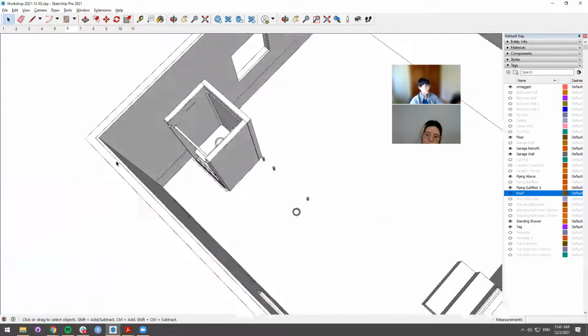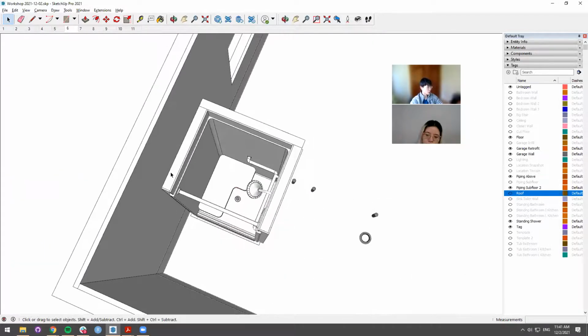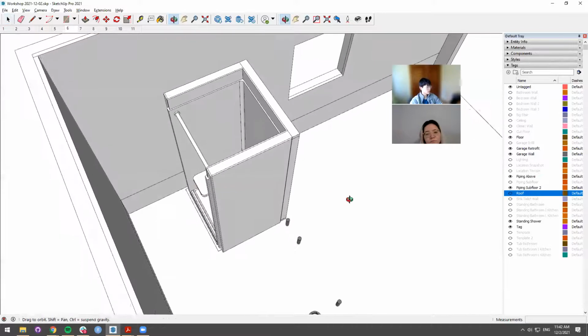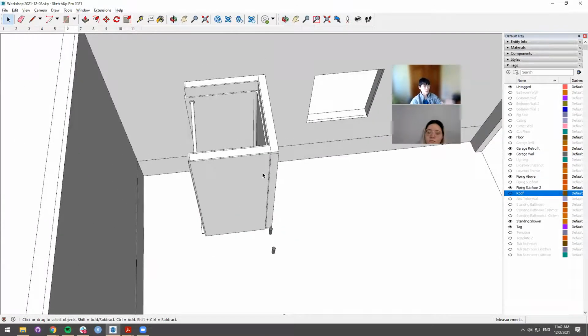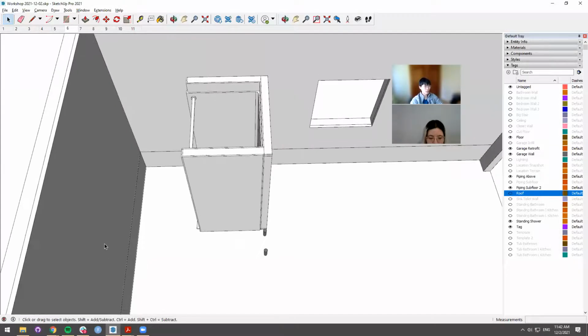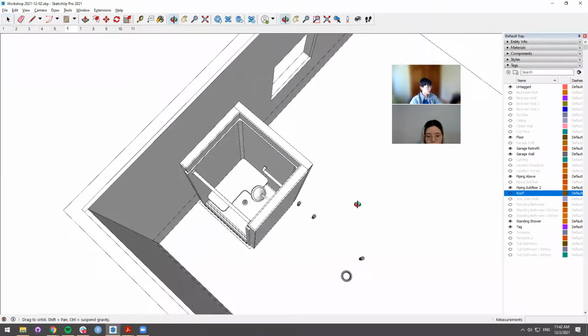First logical one would be kind of far in the back. We're going to look at the transfer shower arrangement. So you place this object, which is 3 walls and a transfer shower already roughed in and framed. And it's got enough of a 3-foot clearance. And notice that part of what makes this specific configuration of a duo efficient is that you don't really need extra walls on the far back side of the bathroom. So that could be saving space and material as well.